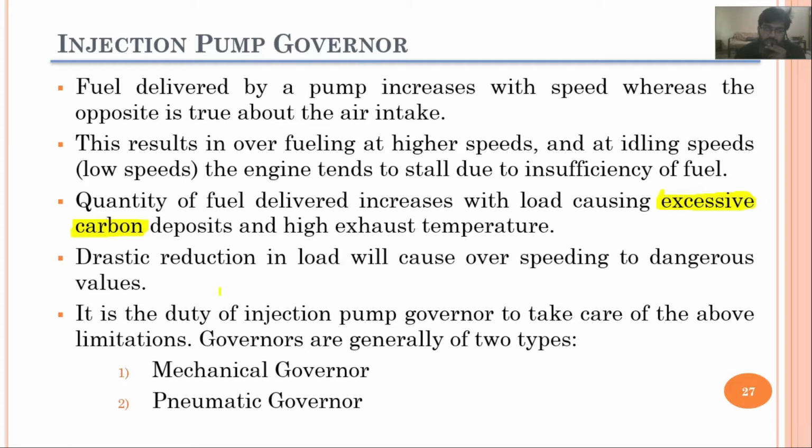So it is the duty of the injection pump governor to take care of the above limitations. What are the limitations? At higher speeds, the governor needs to take care of the overfueling phenomenon. At lower speed, the governor has to overcome the stalling problem.